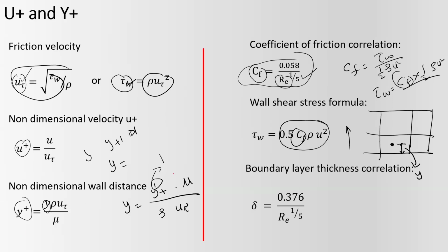And friction velocity, we calculated from here, let's say this is equal to 0.2, and the viscosity, let's say, is equal to 1, and density is 1000. I'm just giving examples. So if I put these values in the formula, 1 into 1 divided by 1000 into 0.2, the first cell height, you can write it down like delta y1, is equal to 1 divided by 200.